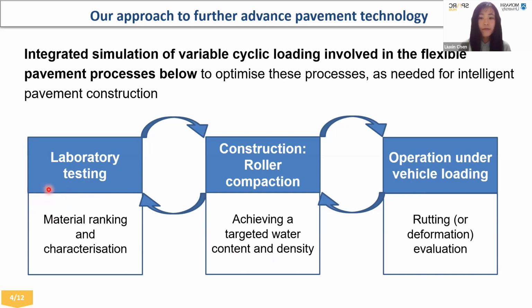Vice versa, if we do a better laboratory test, which better replicates the pavement response, eventually we can get a better estimation of rutting. The key tool in this integration is the computational framework, which should allow capturing the essential features during these processes.